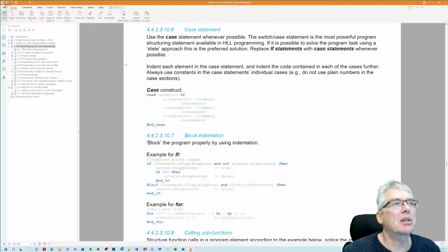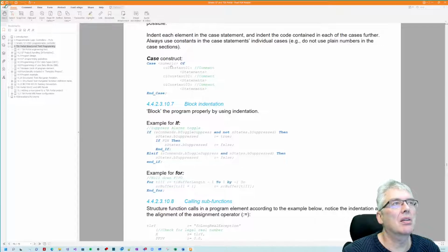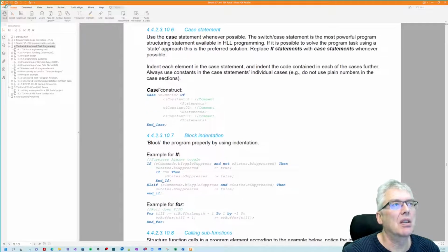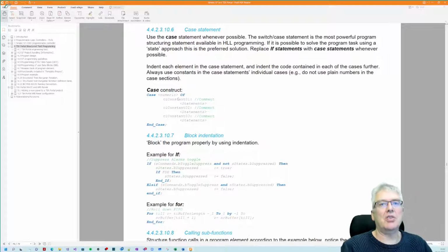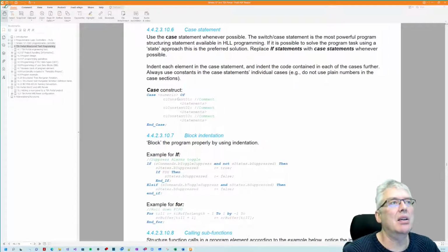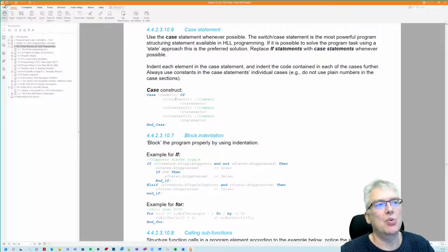Here's the case statement. It should look like this. And in structured text, for now, the case that you are testing is numeric. So this is a number, and then you would use a constant to say what this state means. If it is the number 1, okay, you write 1, but if it means something else, the state you are in or the case you are in, write what the case is doing.